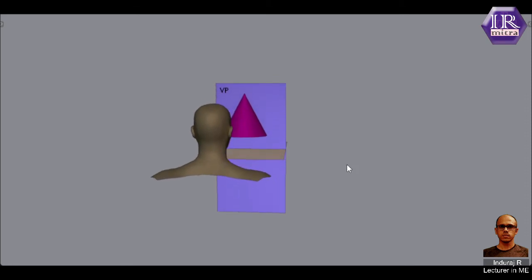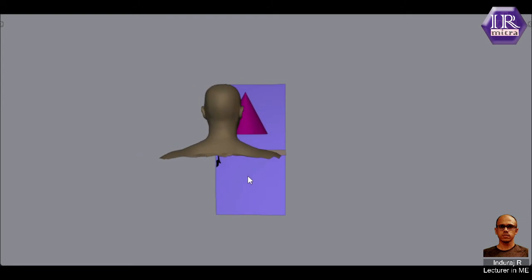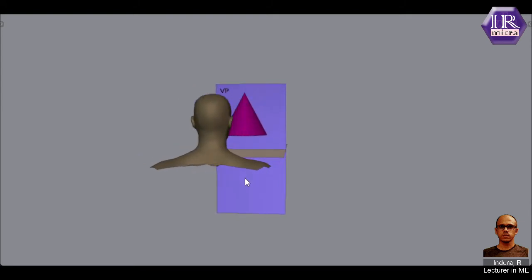This is applicable for any quadrant. For any quadrant, the position of the observer is not changing. He is viewing from this position only, and the view he is getting is known as the front view. Now the doubt that many will have is, if the object is in the third quadrant, how is the observer going to see it? Here we have to apply some imagination, like all the HP and VP are transparent. In that case, the observer will not have any difficulty seeing the object even if it is in the third quadrant. The front view is clear for us now.